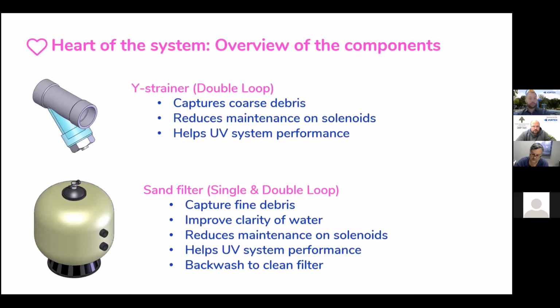Your sand filter is going to capture fine debris as well, improve clarity of water, reduce maintenance of solenoids as well, help with UV system performance, and backwash to clean the overall filter.